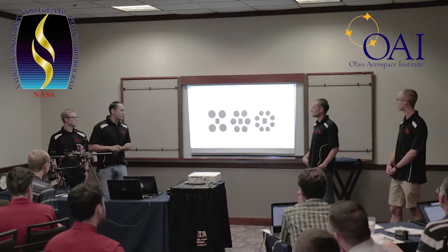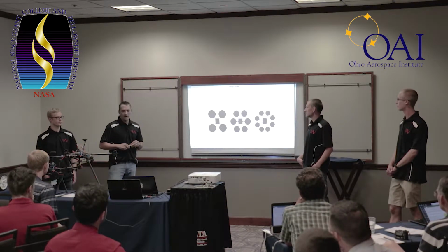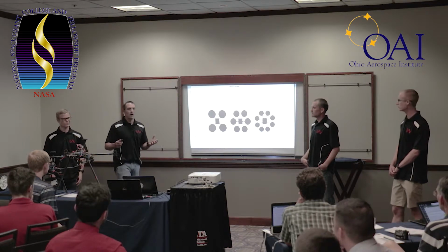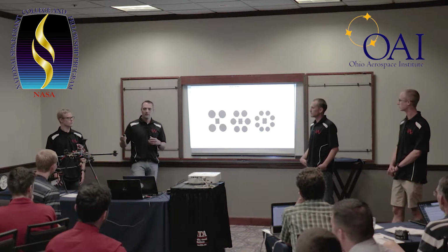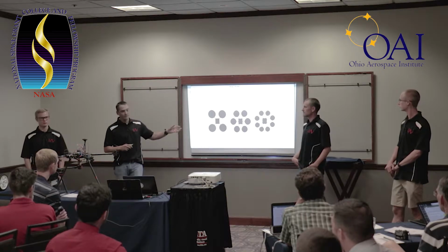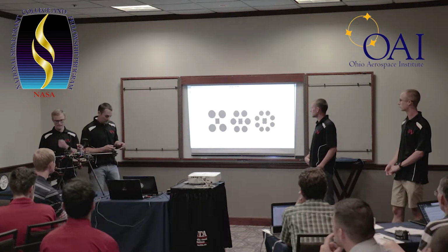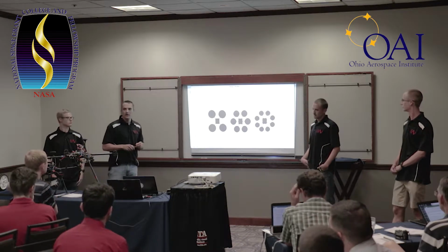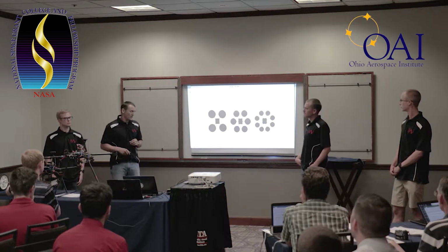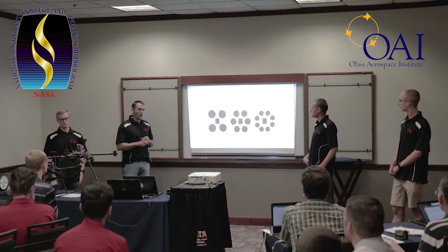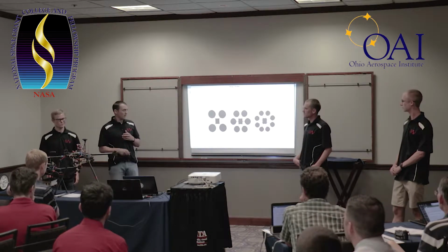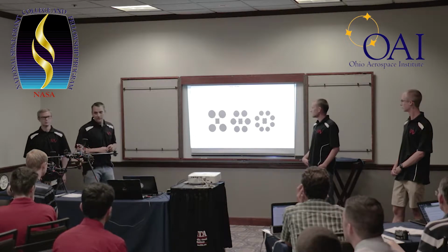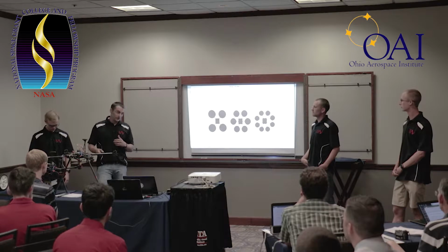Really, a lot of this stuff lingers from design studies for drone optimization platforms. Everybody's familiar with quads, and that's the easy pick of the litter. A hex or an octo are very similar. You'll see a lot of these platforms in use for high-end professional platforms. The idea is fault tolerance, right? You can have a motor go out and it's still a more stable platform than it would be over here.